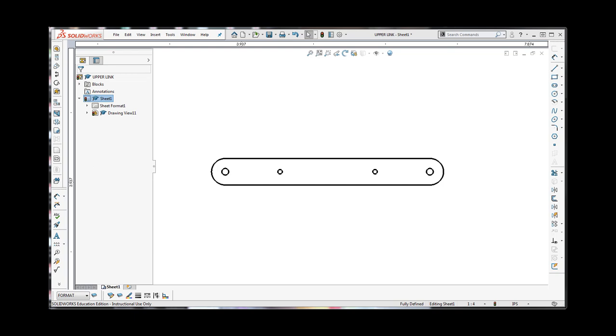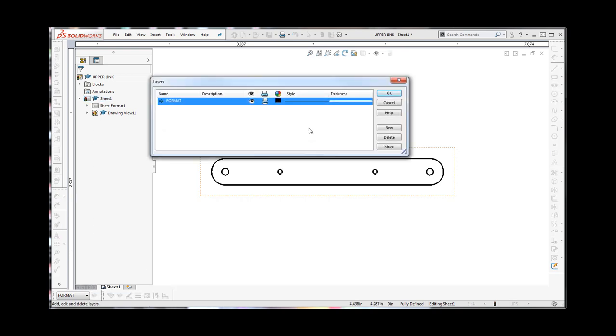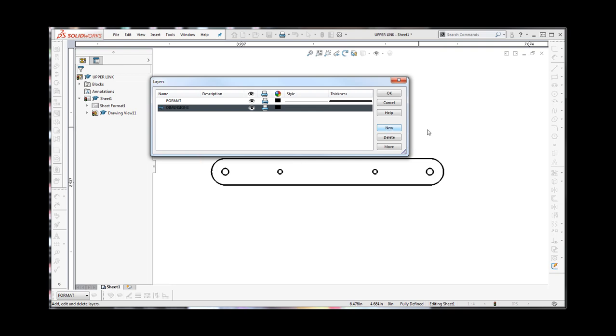In this video, we're going to review how to insert a block and add some ordinate dimensions. So the first thing I'm going to do is add some layers. So we'll put a layer for dimensions, and one for, we'll just call it axes, and one for forces.